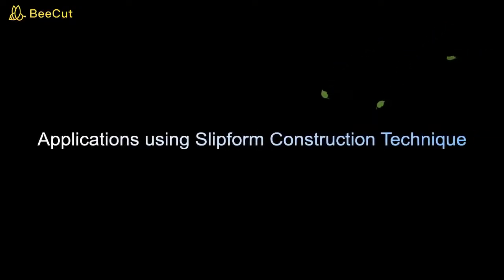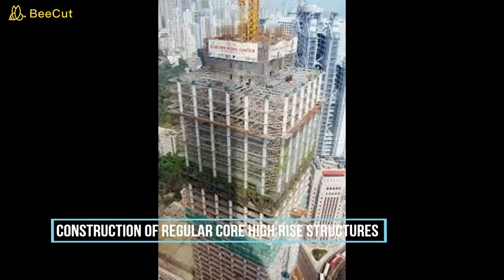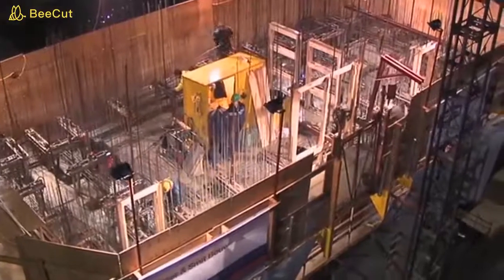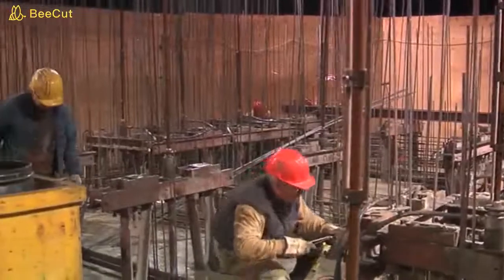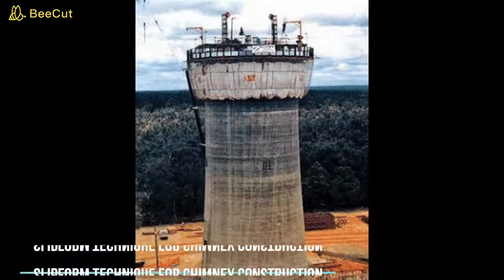There are 4 applications using the slip form construction technique. First, construction of regular core high-rise structures. This slip form design method used in the construction of high-rise buildings is carried out by vertically extruding the portion of reinforced concrete. This method easily builds standard shape core structures and buildings.